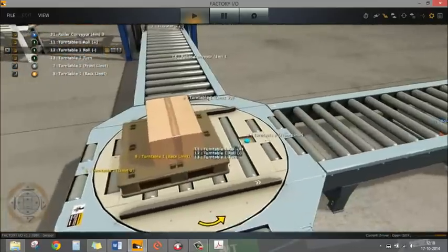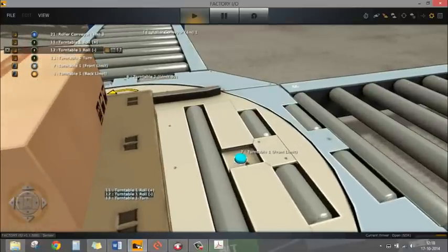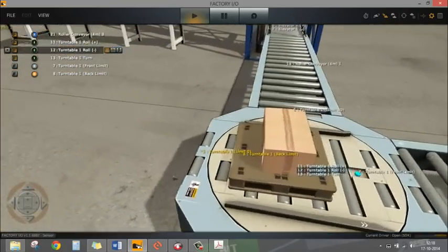So here, you can see that the range is very small. The box is almost above the sensor. So you can save your cost by utilizing a capacitive sensor in this application. Here a diffuse sensor can also be used, but because of the cost we can use a capacitive sensor. And also because of the application.